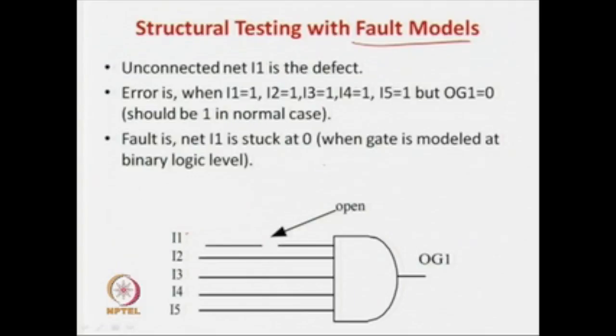So, I am not interested in finding out whether this gate is functionally correct or not, but rather I am motivated to know that there should not be any defect in this circuit, because that is testing. Testing in case of a circuit is not to ensure that the circuit is functionally proper. That is very difficult, because it takes a long time. So, what I want to do is find out that there are no defects. But testing for no defect takes a long time, because there are a lot of physical defects, a lot of crystal defects, and it goes into physics.